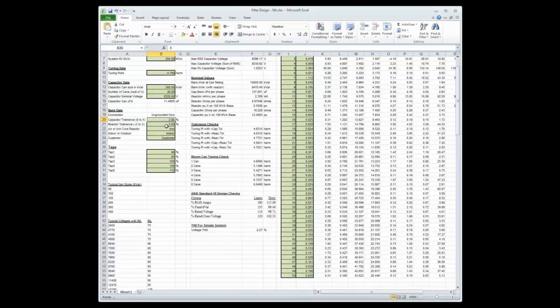And when they're in that positive tolerance range, you'll find that your kVAR is going up significantly. I had a condition where, after designing and having an install on a harmonic filter, during the commissioning effort, we actually pulled capacitor units out of it because, on average, after measurements, I discovered the tolerance was about 7% high on the entire bank.